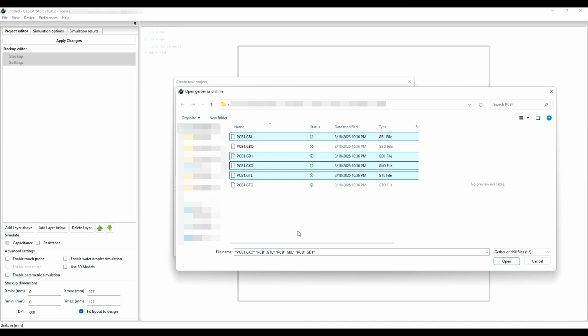This means that the unused areas may be reduced in size, or that silk screen contents outside the board may cause the board to grow in size. It is therefore advised that you generate and import this layer. We also import the top and bottom overlay layers, which contain the silk screen layout.